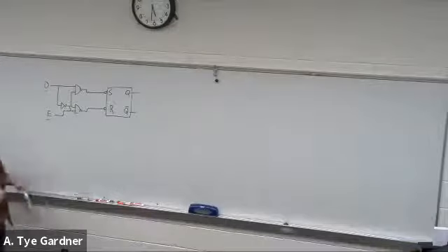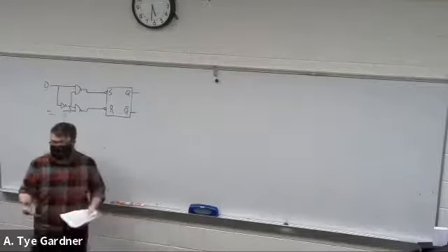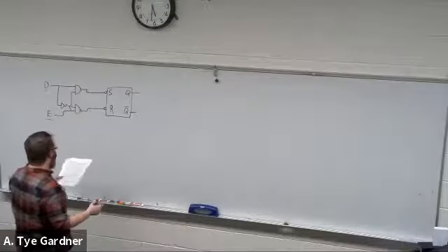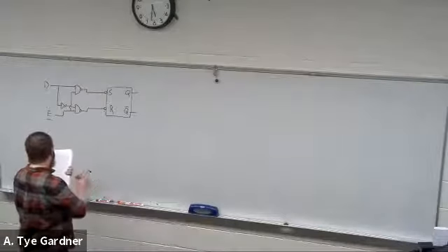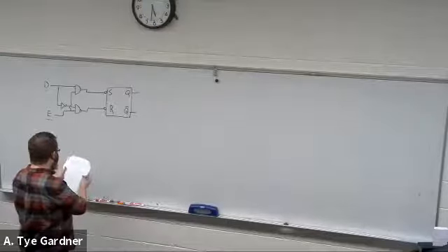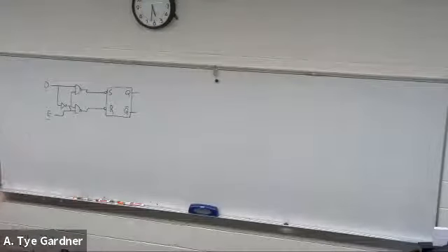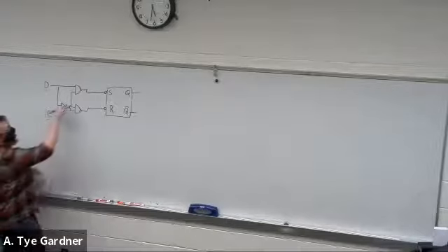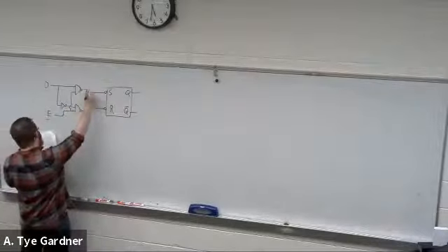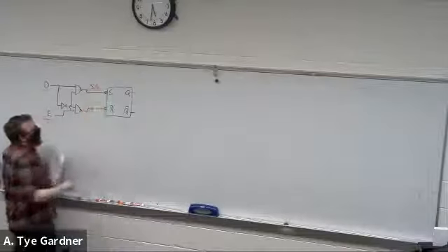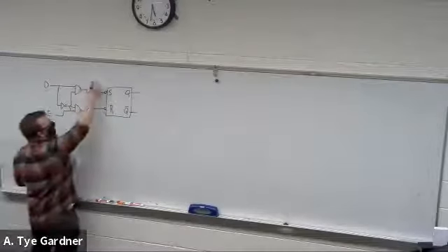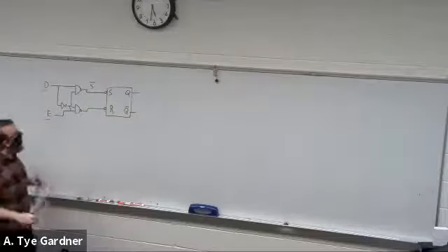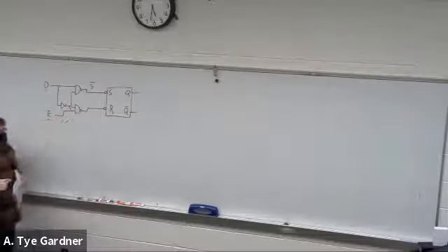So let's go ahead and actually do an example here for these timing diagrams. This one's a little bit more interesting than the other one. Actually, one second, let me double check. I want to do something first. This one has actually a little bit of an issue that I don't like because of what you have to do, right? So this is really a set not low, so it's inverted. So we could also call that not set, right? Because of this NAND gate inversion.